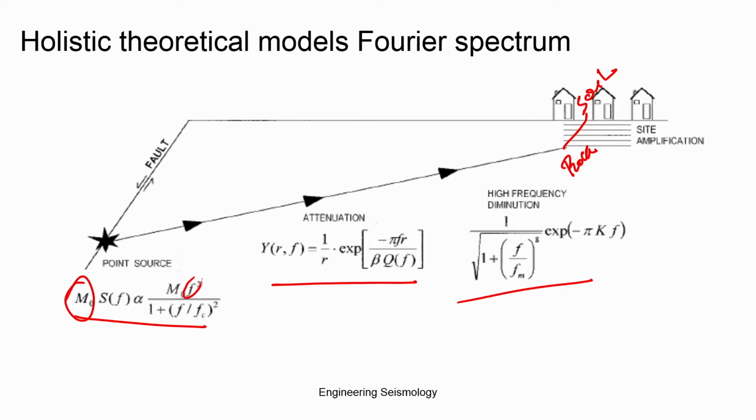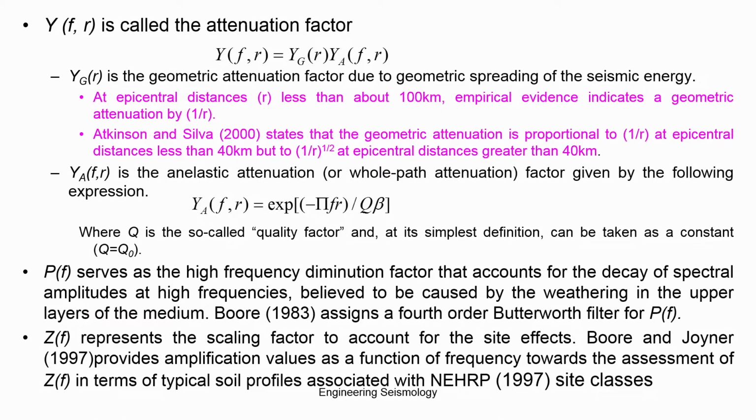Okay. Then the frequency content at which you are looking, the corner frequency, f is the corner. So, attenuation is expressed as a function of your frequency and the travel path, R. That is also expressed as a quality factor Q. Again, the attenuation characteristics of the path express the frequency content of the motion, the particular frequency you are looking for, and then the kappa factor, those kinds of things are used. So, knowing these parameters you can get a spectrum for a given site.